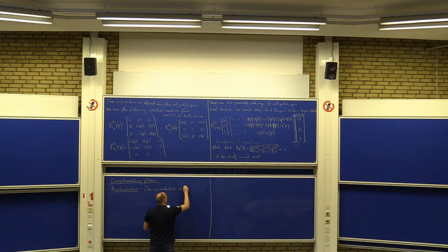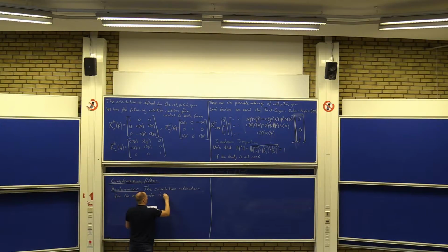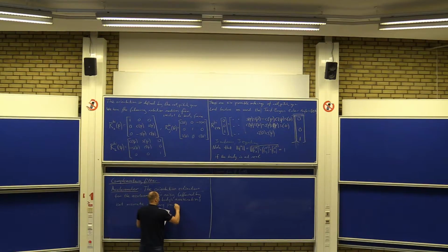So the orientation estimation from the accelerometer is noisy, but it's accurate over long periods of time, under the assumption that it doesn't continuously accelerate or something like that.